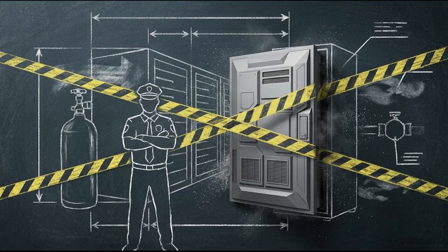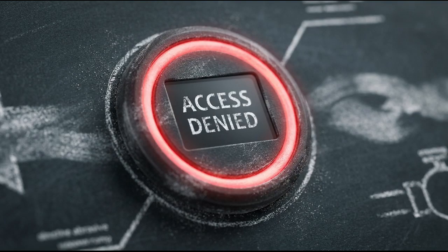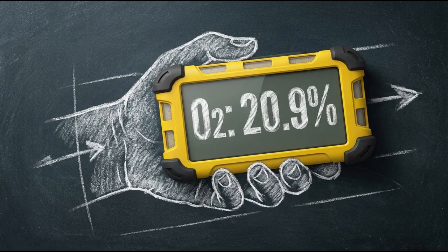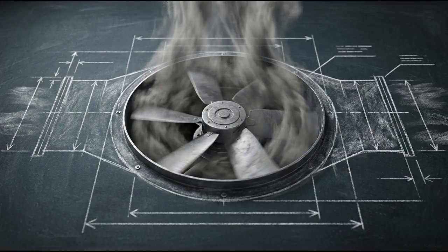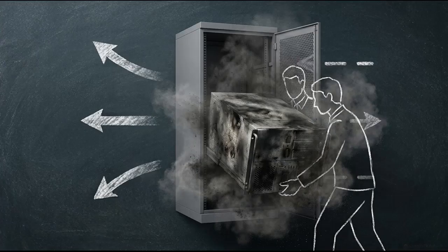Re-entry is strictly an authorized process, never an automatic reset. Incident commanders must maintain physical access control, utilize calibrated atmospheric monitors to verify safe oxygen levels, and engage approved mechanical exhaust ventilation to clear the inert gas before allowing technicians to assess the damaged server.